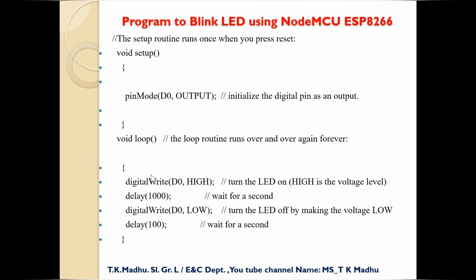So once you execute this or download to the NodeMCU, the whole loop will be continuously executing. So this is the program for blinking. So when you buy a NodeMCU in the market, if you directly do an IoT application and the board is not working properly, you will not be knowing that. So better download this blink program, and there is an inbuilt LED in that. It starts blinking. Then you can decide that this board is working fine, and you can go with the further experiments.